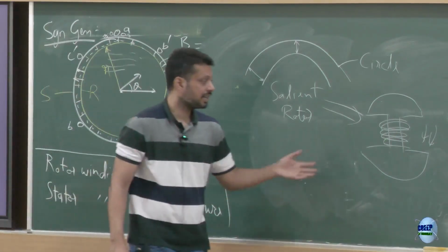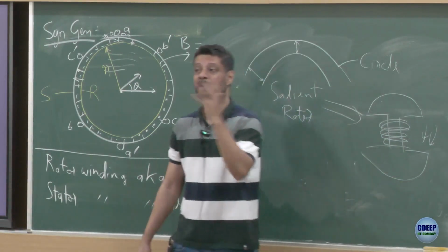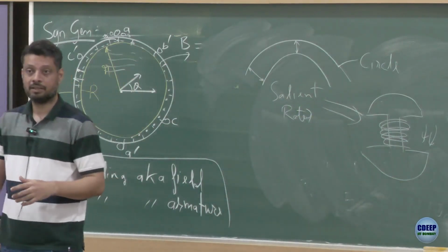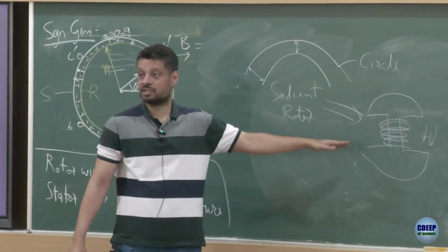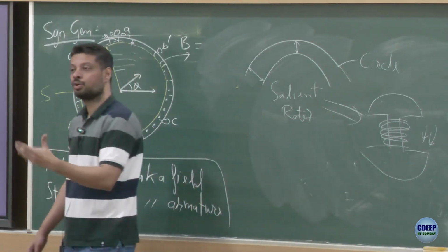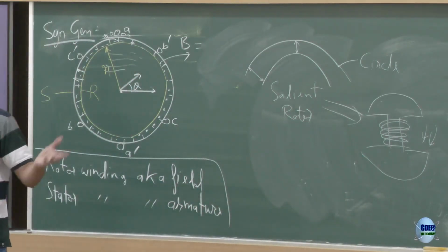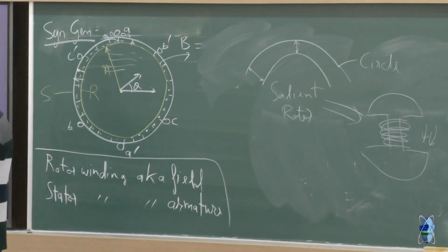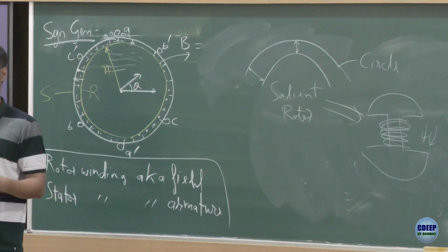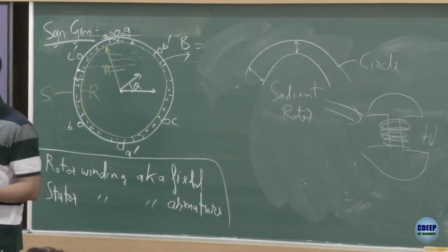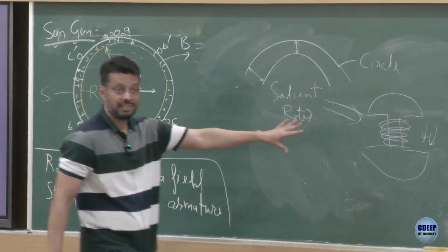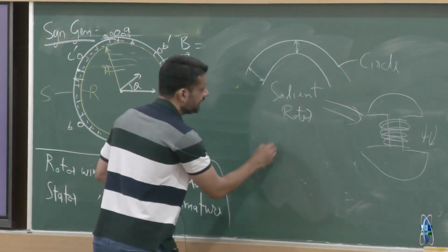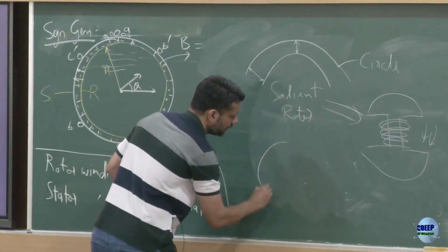The structure is not very suitable for a very fast rotating type of machine, and therefore this structure is popular wherever your rotor rotates slow, such as hydro, water will come and rotate slow. Wind, you have seen the wind, anyways it rotates slow, doesn't really rotate very fast. But the other technologies where you are using steam, you are using gas, the RPMs are high, it rotates really fast. So you don't use this, you use a cylindrical one, and this is how it looks like.